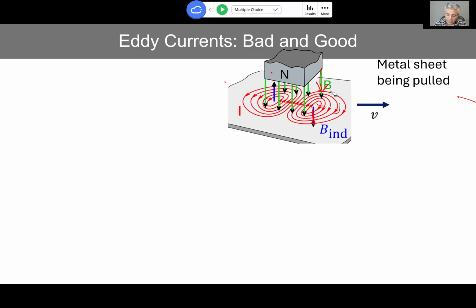So over here, when it's leaving over there, what happens? It's going from a high magnetic field or flux region to a 0 flux region. So that means now flux is decreasing. So to oppose that, it has to generate the induced EM field in the same direction.